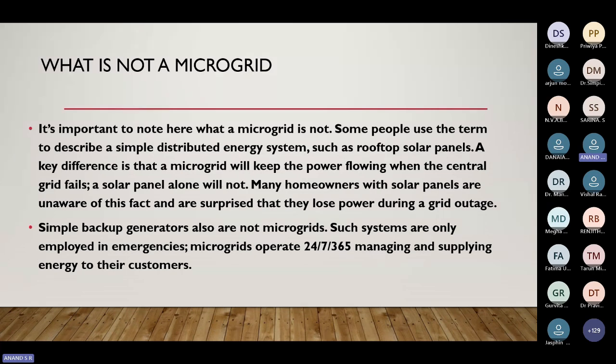They have to maintain the refining activities; they cannot stop when power goes. So what they do is they have an internal generation, and the minimum generation requirement could be something like 100 to 150 megawatts. So only the remaining portion can be taken from the grid.